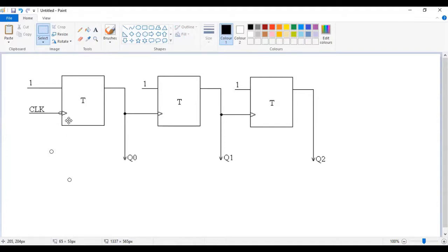Now it's okay. So you're just going to do something like this, and then put all the clocks to be active low. Okay, and then if you want to have now a modulo 10 counter, it means you will need to have at least 4 flip-flops, because if you have 3 flip-flops, it's going to stop at 7. So you're just going to have 1 more flip-flop.